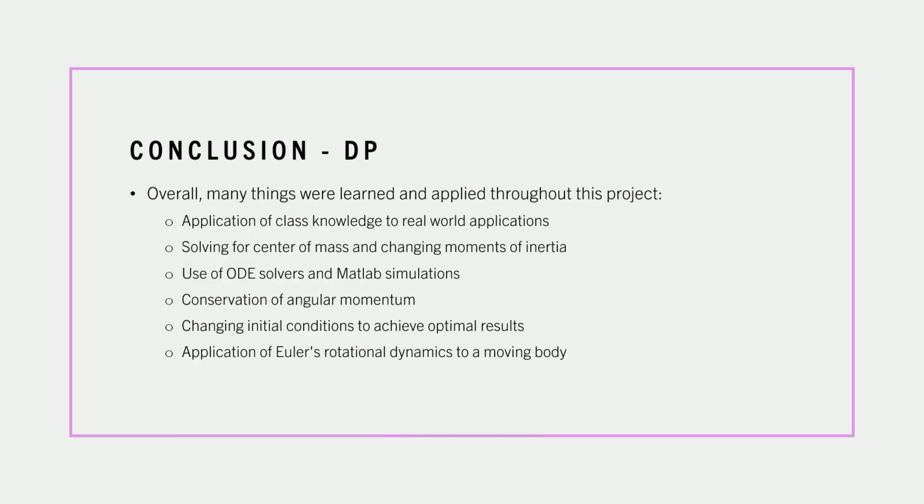In conclusion, this project provided a valuable opportunity to bridge theoretical knowledge with practical application. Through the process, we applied class concepts to real-world scenarios, calculated center of masses and varying moment of inertia, and utilized ODE solvers with MATLAB simulations. The principles of angular momentum conservation and Euler's rotation dynamics were essential in analyzing the diver as a moving rigid body. By modifying initial conditions, we were able to explore and achieve optimal results, demonstrating the intricate interplay of translation and rotational dynamics in diving motion.